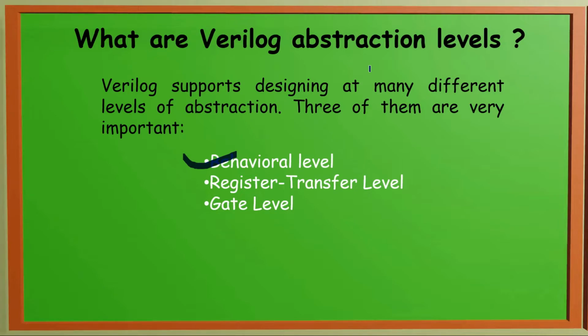And then the most bottom level is the gate level. What happens in gate level? Within the logic level, the characteristics of a system are described by logical links and their timing properties. The gates will have a definite logical value. Either it will be 0, 1, X or Z. These are called predefined primitives.